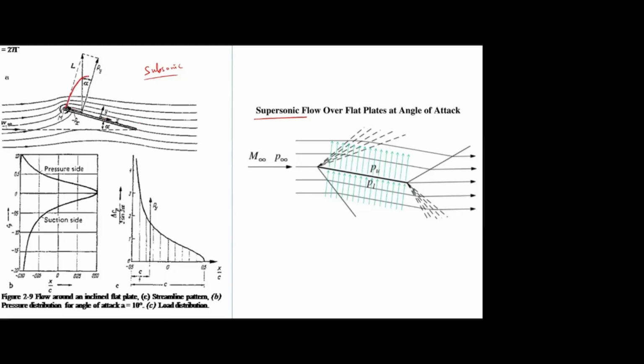can get the pressure distribution like that, almost similar to the aerofoil. Okay, the only difference between flat plate and the aerofoil is that here the stalling angle will be more. This may be stalled at 15 degree and this may stall at 7 or 8 degree itself. Okay, because of this curved surface, the stalling angle is increasing.